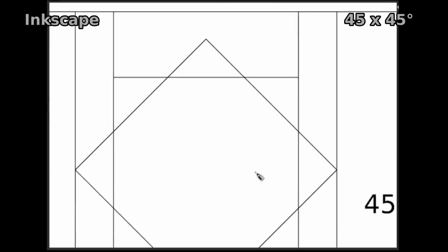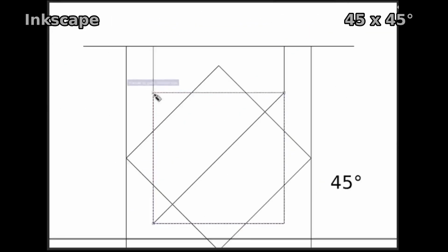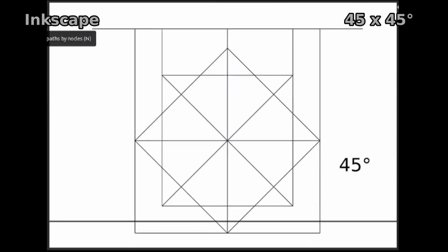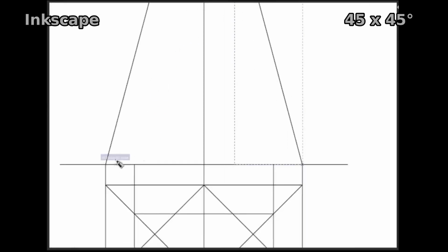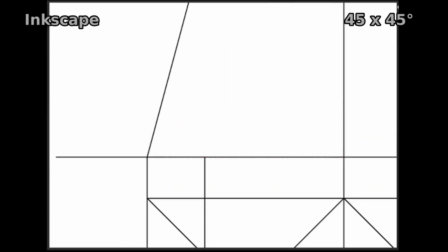This is the same type of application with a different approach in Inkscape. The bottom orthographic plan is generally plotted in the same way. The convergence of the first 2 receding lines are made symmetrical by using Inkscape's built-in ability to snap to specific intervals of preset degrees, in this case 15 degrees. Next, the total width is marked with a rectangle, then a new section is added in this rectangle to mark the smaller bounding box of the unrotated square.